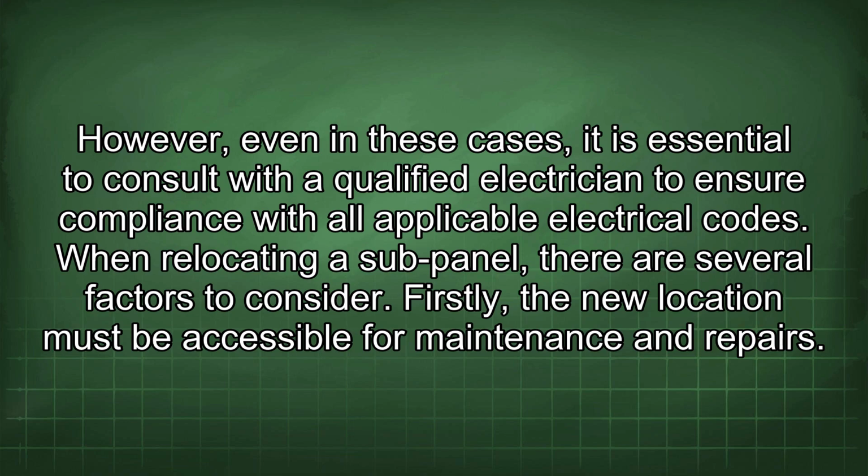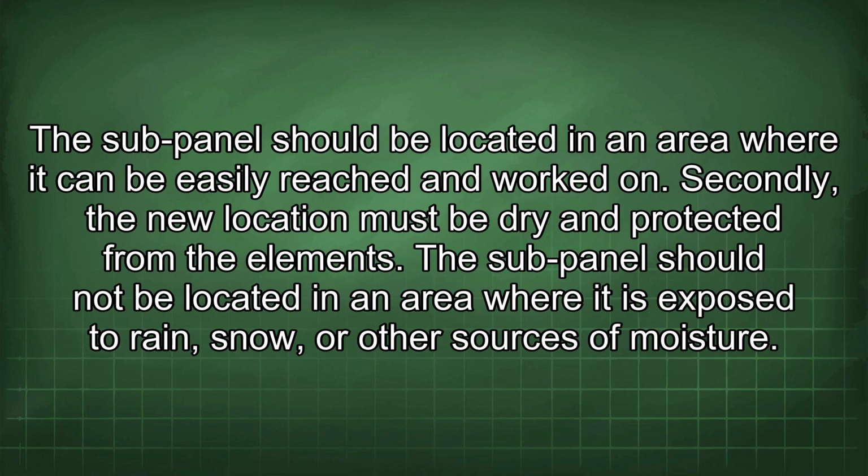Firstly, the new location must be accessible for maintenance and repairs. The sub-panel should be located in an area where it can be easily reached and worked on. Secondly, the new location must be dry and protected from the elements. The sub-panel should not be located in an area where it is exposed to rain, snow, or other sources of moisture.